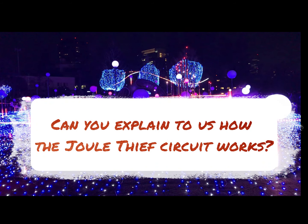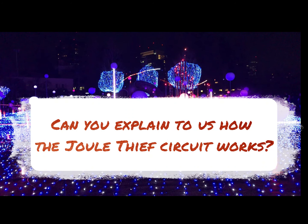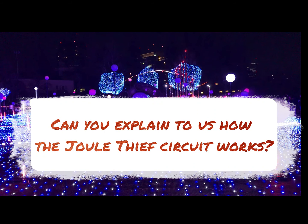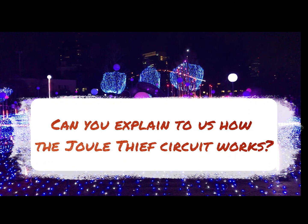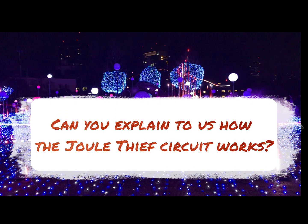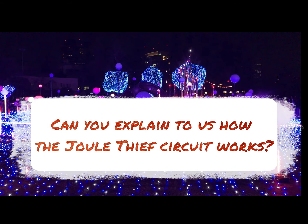This charging and discharging cycle of the inductor continues, creating a high-frequency AC waveform that is smoothed out by the output capacitor, resulting in a steady DC voltage output. In summary, the Joule Thief circuit works by using an inductor, a capacitor, and a diode to create a high-frequency AC waveform that is smoothed out to produce a higher DC voltage output than the input voltage. It's a simple and efficient way to step up the voltage of a DC power source.